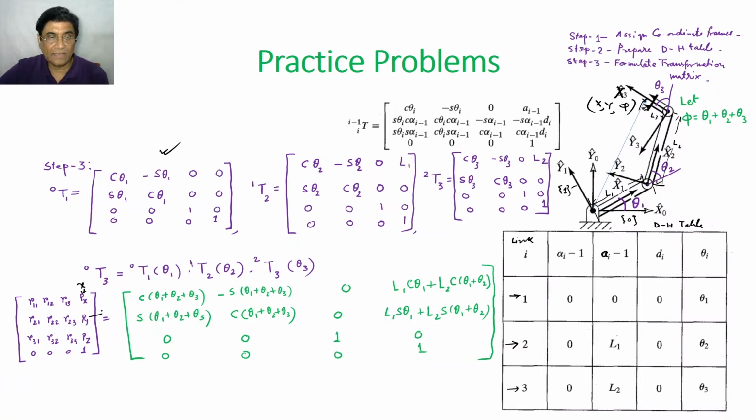So if this equals, say, x, and I am calling this y, and since this is 0 because I am considering a plane, now I have defined a point here, a pose here, x, y, and phi. It's no more a point, it's a pose, meaning it has orientation. That means it could be something like this. So this point is xy, and this phi is the angle with respect to the z axis, which is perpendicular to the plane of the board.